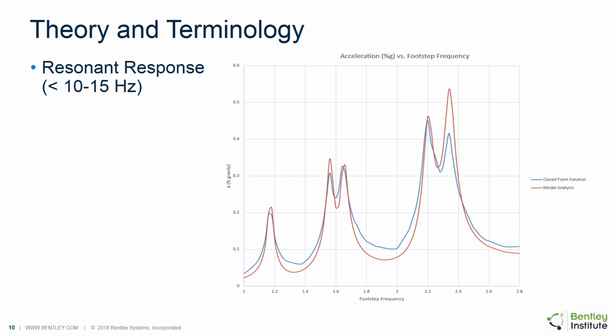So that would explain why the responses get higher as we travel further right on the plot, because the lower level footstep frequencies are likely only aligned with higher harmonics, whereas as we move further to the right, our lower harmonics might actually be aligning with natural frequencies in the floor, and those lower harmonics have higher dynamic load factors.